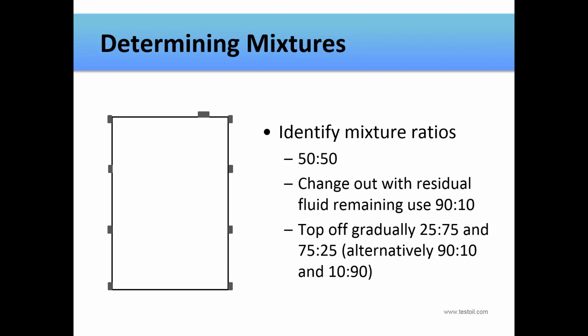So in general, the methods involve making one or more mixtures of the in-service lubricant and the candidate lubricant, heating and then cooling the mixtures, and then observing the mixtures for any sign of incompatibility, such as cloudiness or the presence of sediments.